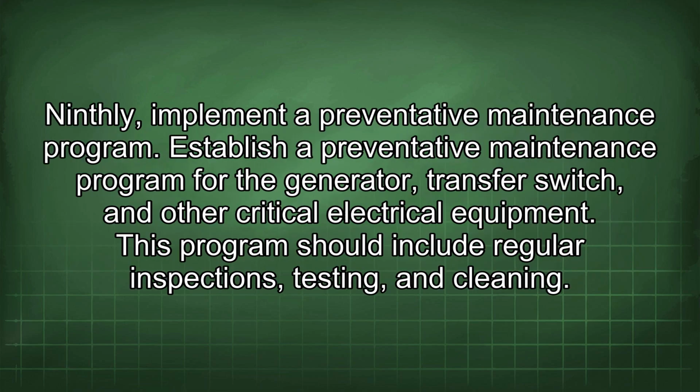Ninthly, implement a preventative maintenance program. Establish a preventative maintenance program for the generator, transfer switch, and other critical electrical equipment. This program should include regular inspections, testing, and cleaning.